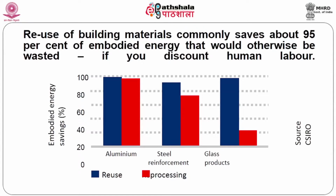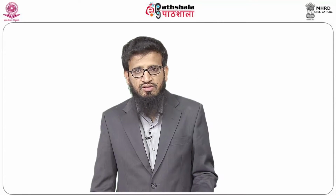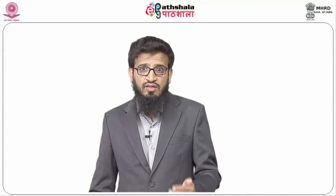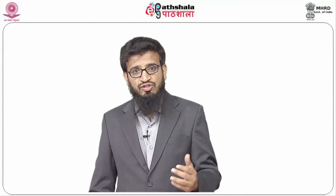Similarly, this chart which we have put over here is a very interesting chart. The reason is, aluminium, as we saw in the previous slide, uses a huge amount of embodied energy, but it can be recycled. Almost close to 95% of it could be recycled, which means that since initially we are using a huge amount of embodied energy, but at the same time that is not going to the landfill, it can be recycled to 95% and reused, which means that the embodied energy in the extraction of bauxite and other things can be reduced drastically.